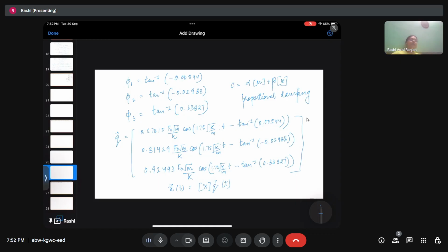Well, then it becomes a complex case because in that case, as I've told you, the concept of mode shapes and the contribution of mode shapes and modal frequency that already has come out because of the damping present and the forcing. Damping is going to damp out the transient thing, contribution of the natural frequencies, and the forcing is going to impart the energy to the system in such a way that it is going to oscillate with a frequency which is equal to the forcing frequency. So there's no contribution of the modal frequency, right?